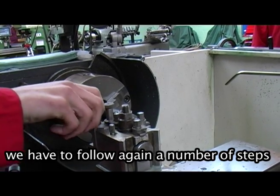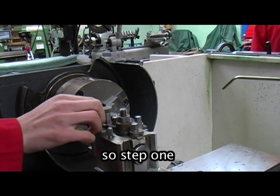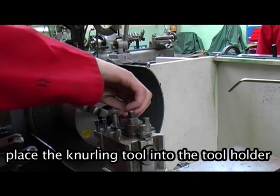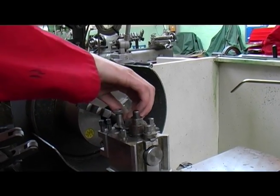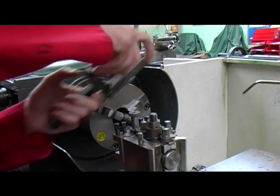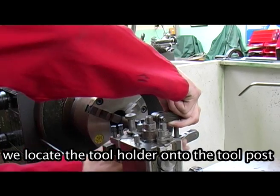Put a knurl, which is a surface finish, onto a diameter piece of work. We have to follow again a number of steps. So step 1, we place the knurling tool into the tool holder. Step 2, we locate the tool holder onto the tool post.